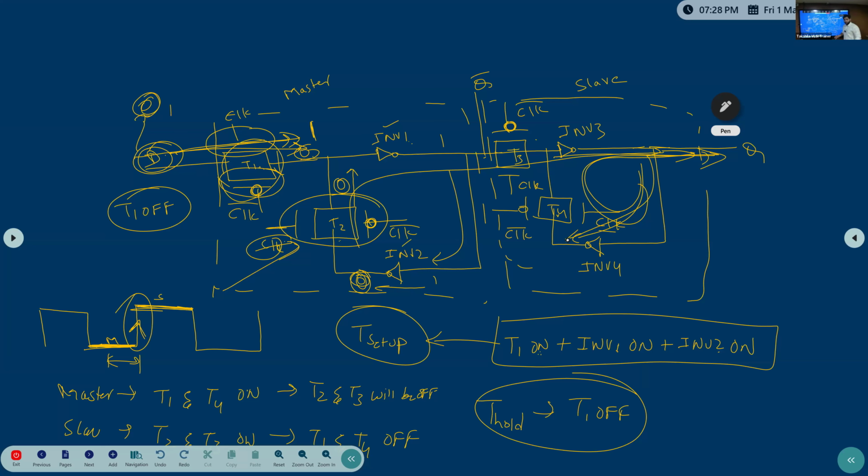It's very, very important. In a flip-flop circuit, how the internal data distribution happens is very important. And one more thing: in your entire career as a PD engineer, you will work very hard to meet setup time and hold time. This is the complete life. Your complete life will be setup time and hold time. It looks very simple, setup time only, hold time only, so we can meet it now. No, there are different methods and different ways to calculate it.